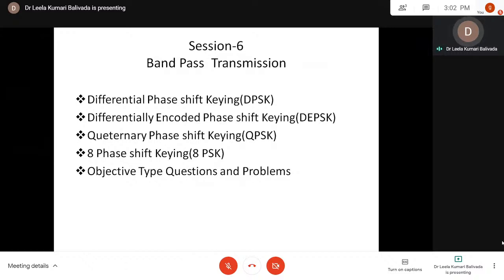So these are the three important techniques, and all three can be implemented using coherent modulation schemes, where the locally generated carrier used at the receiver has to be perfectly in synchronism with the carrier used at the transmitting side, with respect to both frequency and phase. This basically requires a complex carrier recovery circuit and bit synchronizing circuit at the receiving side, which is costly. BASK and BFSK can be implemented non-coherently, but BPSK cannot be implemented non-coherently.